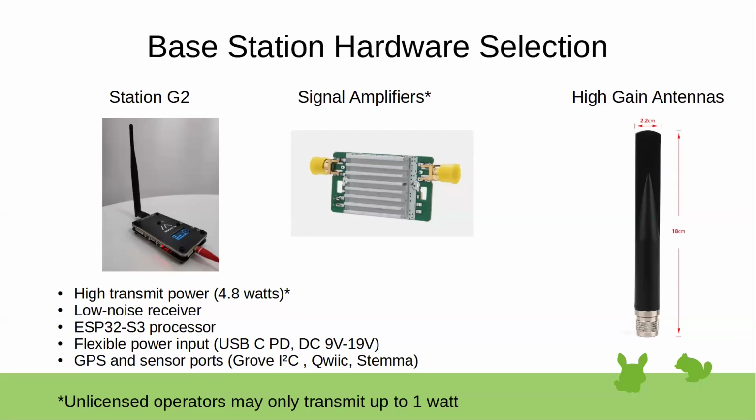I poked a lot of the cheap ones with my NanoVNA, and it shows they're not even meant for 915. They're Wi-Fi antennas, they're just being rebranded. So even when you buy the T-Beams, a lot of the little rubber ducks that come with them are actually just Wi-Fi rubber ducks, and they get like a 4:1 SWR at 915. Yeah. So just buyer beware.